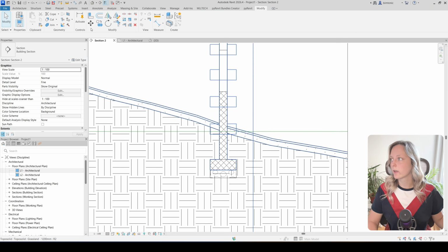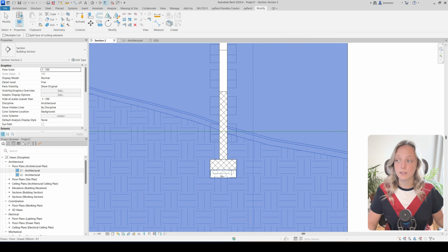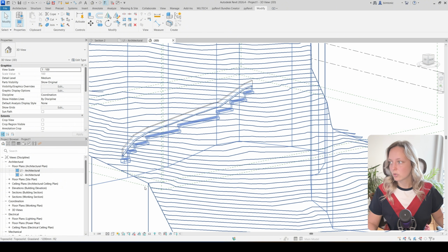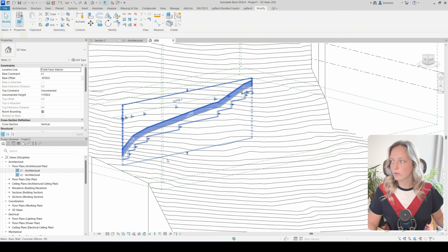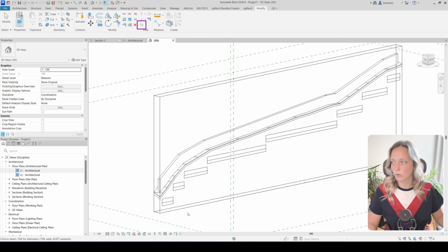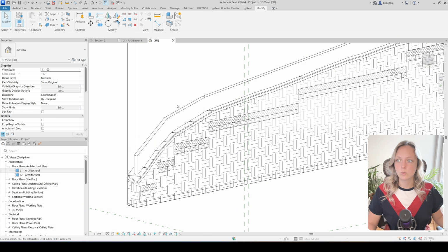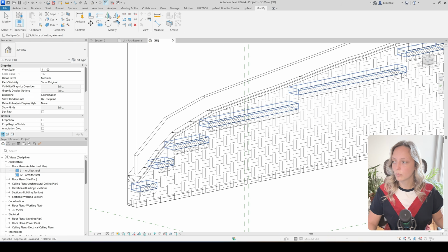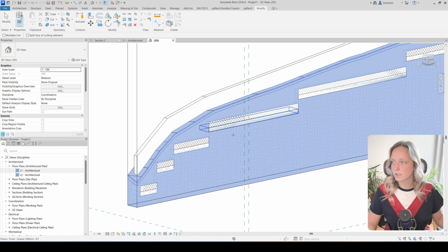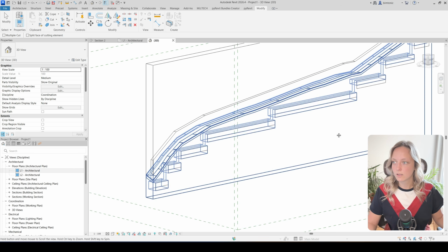Essentially now we also have to cut the topography in the area of gravel. We can also do that in the 3D. I'm just going to get back this topography and I'm going to select this wall and I'm going to use this selection box to get it to look like this. Essentially this way I can see right away which of these gravels are not actually cutting the topography. So I take the cut tool and I first click the topography and then the gravel. And I do this for each of these layers.